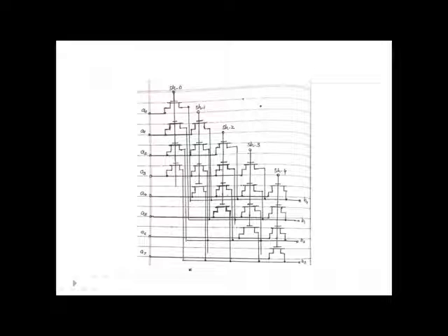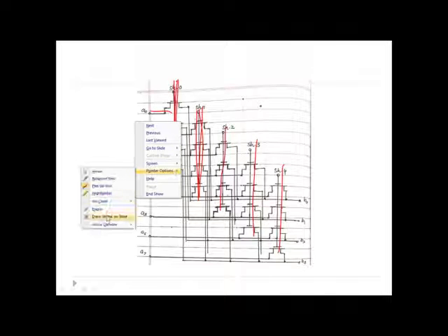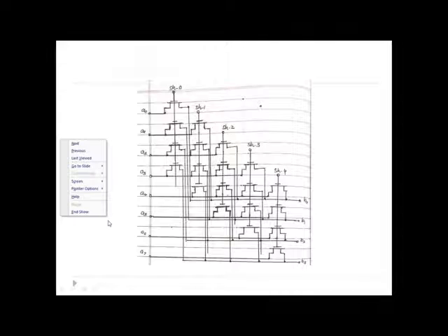It's a simple NMOS connected in a cascade, and there is basically this type of structure. So all the NMOSes which are turned on by one shift signal are connected together. Their gates are connected together here, gates of all NMOSes which are active during one shift operation are connected together. Their inputs are connected to A0, A1, A2, A3, and based on which shift operation you are performing, the outputs are connected accordingly. So you just draw the circuit. The circuits are very easy to draw once you understand the operation.